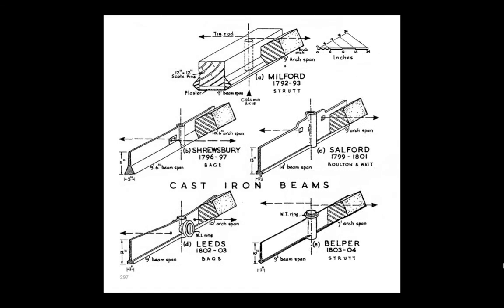Now, Strutt's mill is the one at the top. You can see that there's a cast iron column that holds up a timber beam. That timber beam has these little sideburns of wood nailed onto it that are going to accept the springing point of the brick floor arches. So very, very shallow brick arches that form the flooring for the next level up. And the need to give those brick arches something to push against, right? Something to absorb the thrust that they're going to put onto the beam.